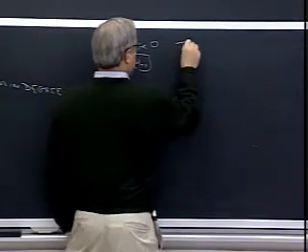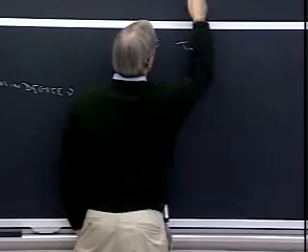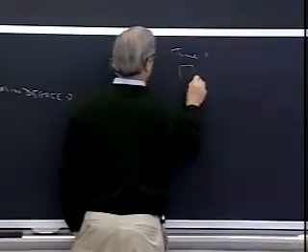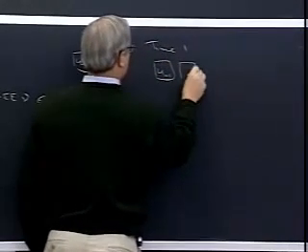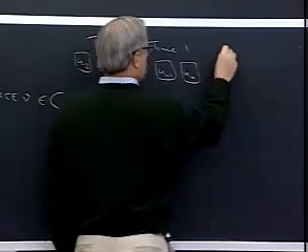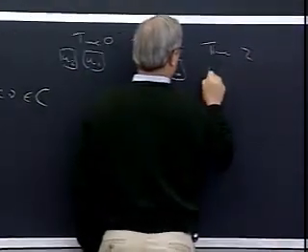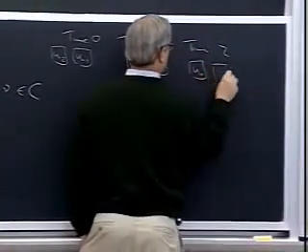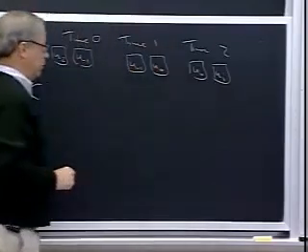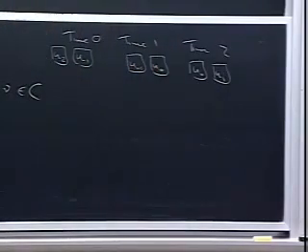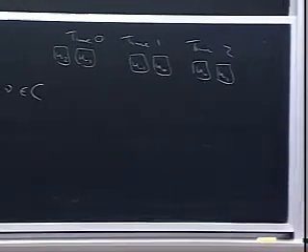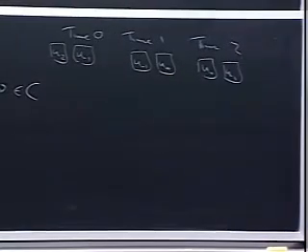At time 1, we need to have in memory u minus 1 and u0. At time 2, we need to have in memory u0 and u1. And we achieve that just by implementing this with a shift register. In the time invariant case, it's very easy, and you all understand it.